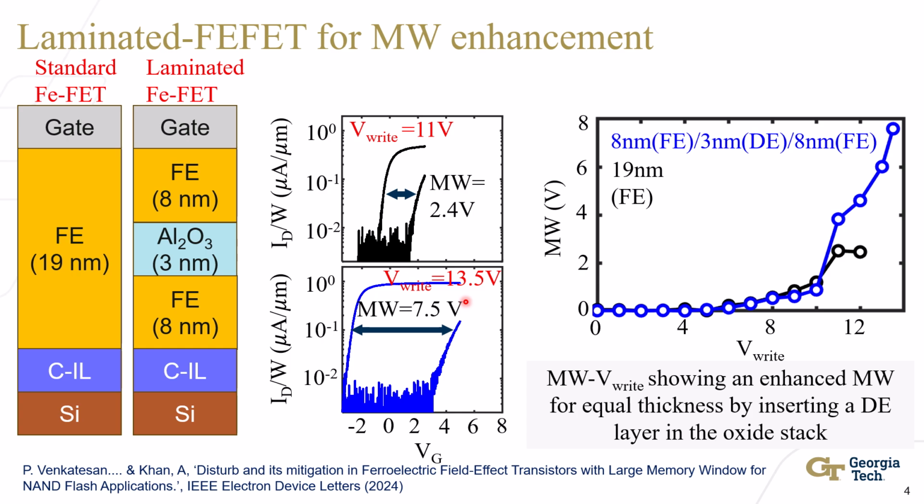There has been a lot of work done recently where different dielectric materials are inserted in the ferroelectric oxide stack to achieve a memory window which is larger compared to a ferroelectric-only oxide stack. In the case where a dielectric material is inserted between two ferroelectric layers, that is conventionally called a laminated FEFET.